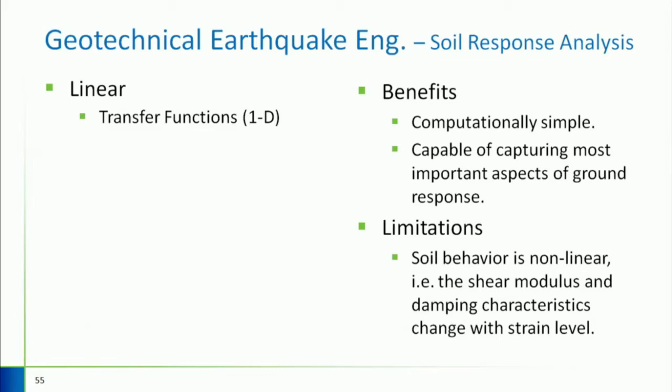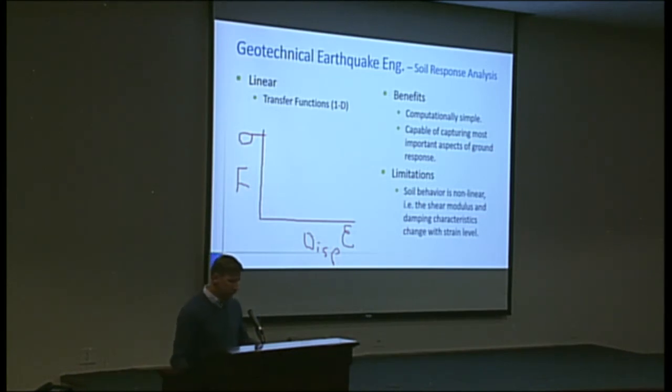So here we have strain and stress. So you guys are not engineers. This here is displacement, and this is force. But they're normalized to a specific area. Generally, when you move an object, it will start to accumulate stress. So as you displace it, it'll get a force on it until it reaches some peak value. In some instances, it'll actually lose strength once it reaches its peak and level off. That's a residual strength. But this is a nonlinear response.